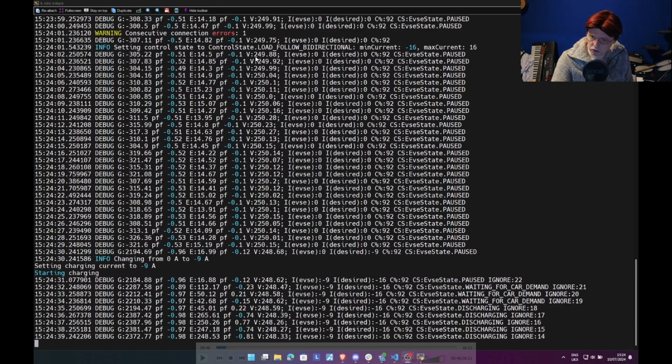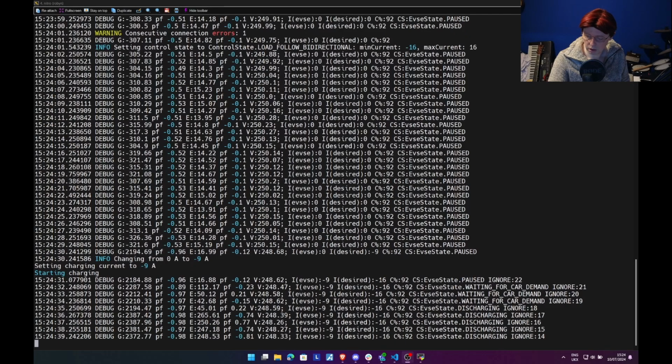The voltage that it's seeing is shown. Mine's pretty high, but the 230 volts is a nominal amount. It can be quite a bit higher and quite a bit lower than that, and still within acceptable tolerances of the range.